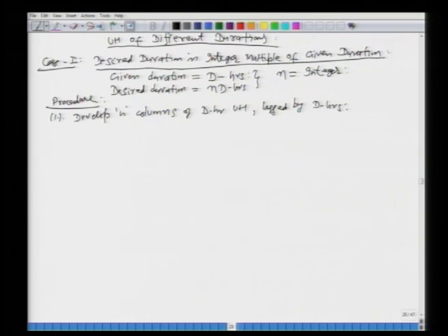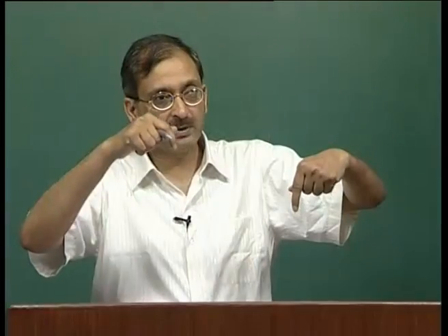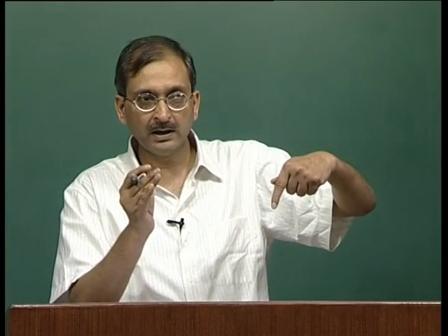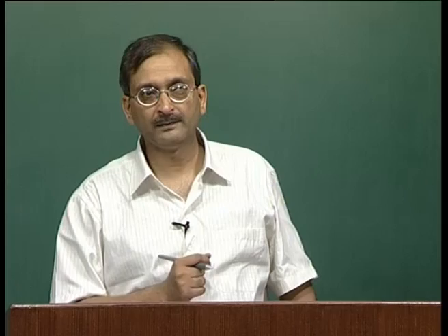What we mean by this step is that, let us say we have the unit hydrograph given to us. So, we have the time base, and at a certain interval we have the values of the unit hydrograph of d hour duration. Now, we want to find out the n times d hour duration unit hydrograph, and let us say for example, the value of n is 3. Now, what we are saying in step 1 is we develop n columns of this d hour duration, that is n is equal to 3. So, we develop 3 columns. So, we just have time versus the unit hydrograph, and then we lag it by d hours once and lag it by d hours once more, so that we will have a total of 3 columns, but the lagging will be done n minus 1 times or 2 times for n is equal to 3. This step will be more clear when we take up the example.